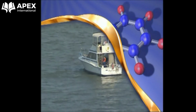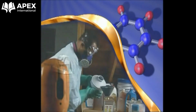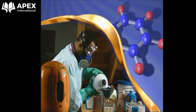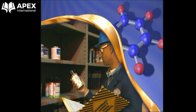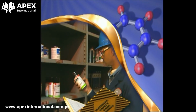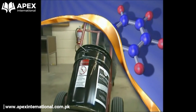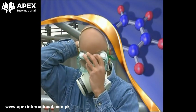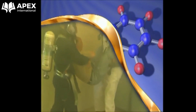You have the power to make hazardous chemicals useful in many ways. You also have the power to use them safely by following some basic guidelines. Know what you're working with, read the label and MSDS, and make sure you understand the hazards and the ways to avoid them. Know how to move, transfer, and store the material safely. Use the right PPE and use it the right way. Know your role in case of emergency.